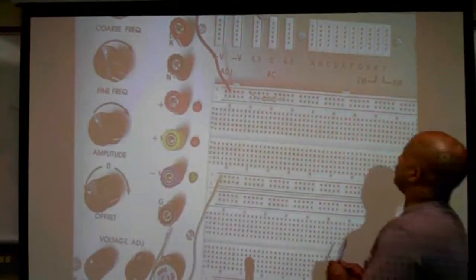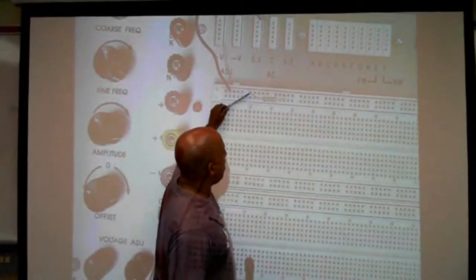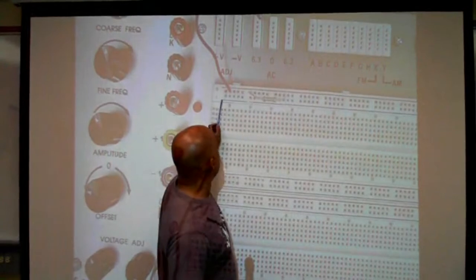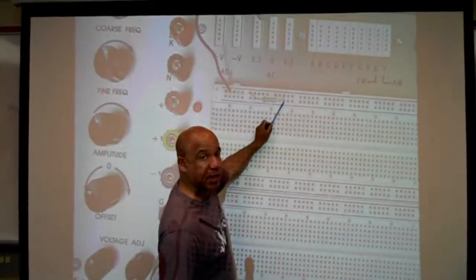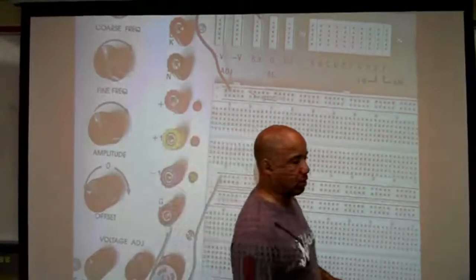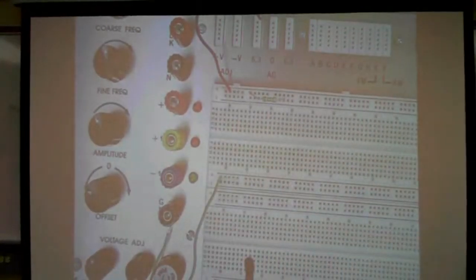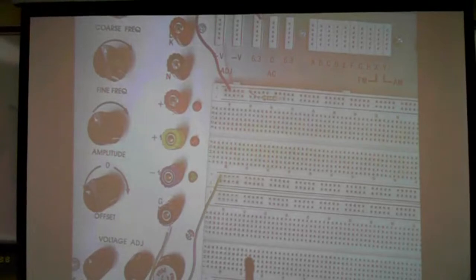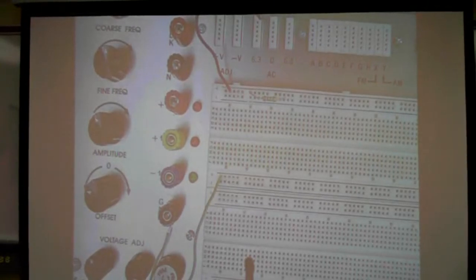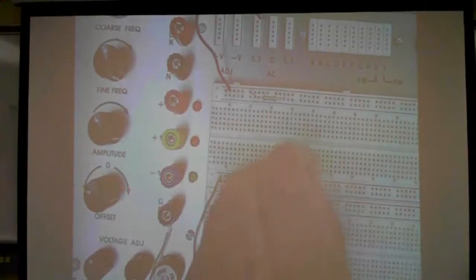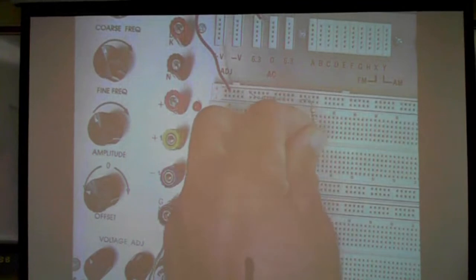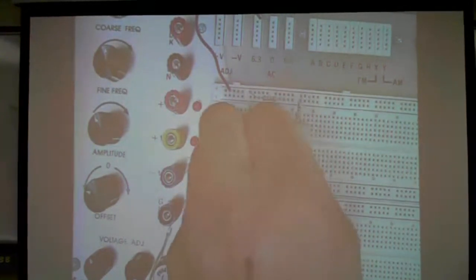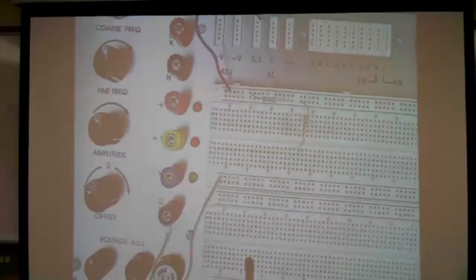Now it looks like it's plugged into that top rail, but actually one end is plugged into the top rail. This second rail, which was all the way across, has nothing plugged in it. So I just have the resistor plugged in there, just for convenience, so it looks more like the circuit diagram. And I take my 680, and I'm going to connect now. This rail is coming all the way down, so I can connect the wire or the resistor anywhere I want, and then bring it over to one of the columns like that.